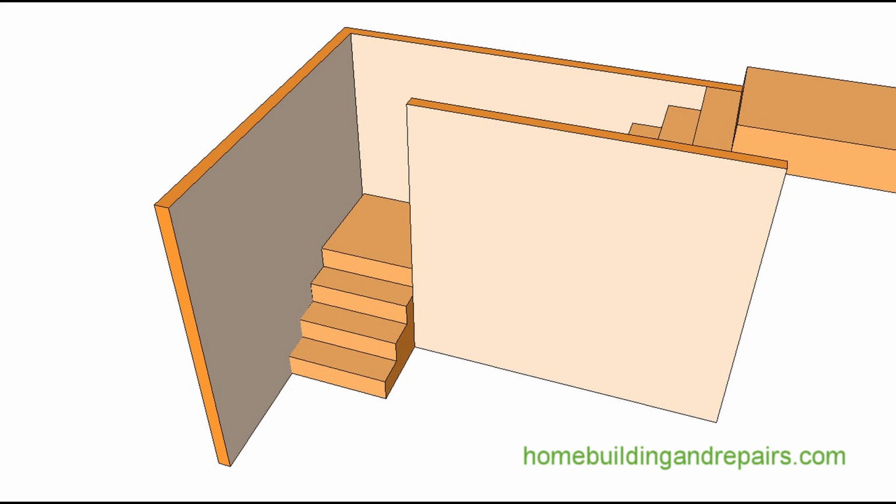And remember, most steep stairways are a result of cramped spaces. They just don't have the room to put the stairway in there, and they do the best they can. And as long as it meets local building codes, which a long time ago they did. I put stairs in plenty of times that had 8-inch risers and 9-inch treads, 9-inch wide treads, and they were uncomfortable and unsafe to walk on.